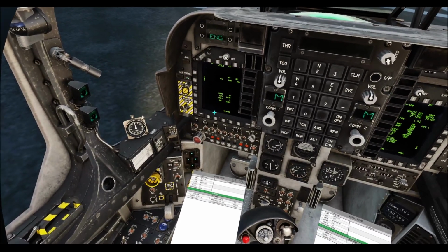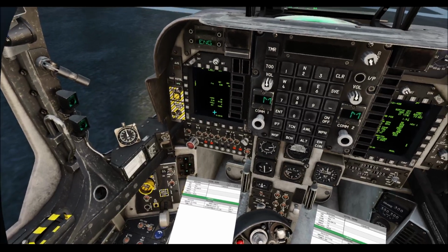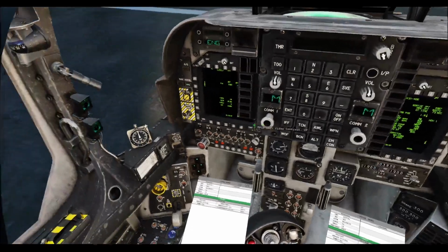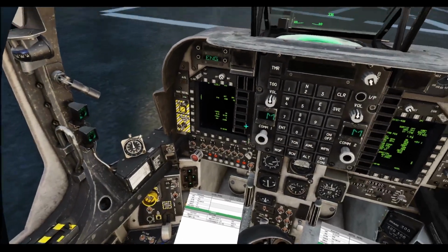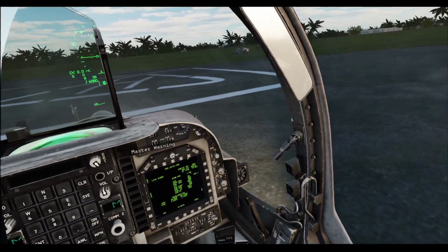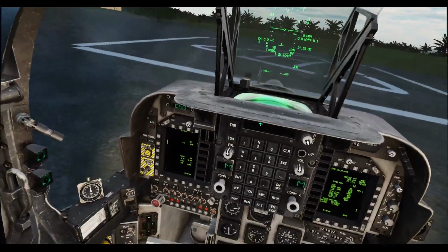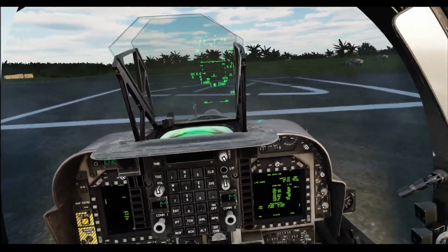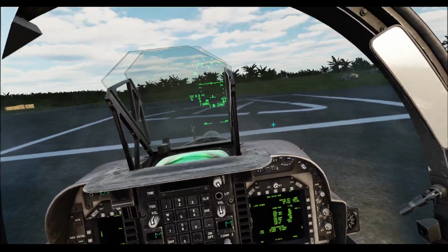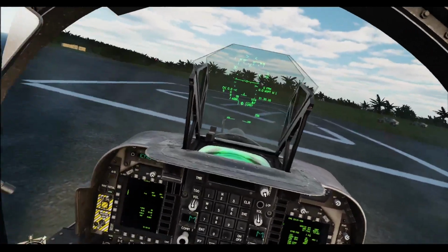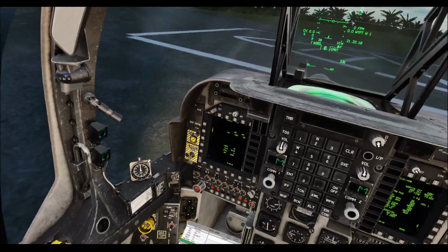So with water on, so wet, 21,080 pounds. We're at 3,800 pounds, so that is 1,700 over. Plus, I've got 1,000 pounds of stores, so that's 2,800. That's within the 4,000 pound ballpark figure. However, it will be a bit tight with those trees there. But we've got enough prepared surface, and then hopefully that's enough clearway for us to get up into the air.